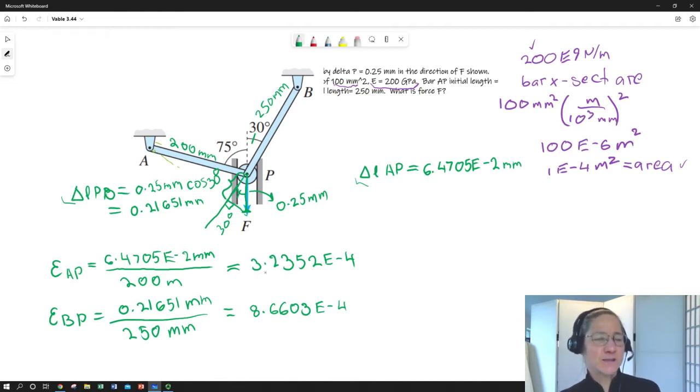We would also expect maybe a little bit more strain in PB, simply because it's oriented closer to the direction of known strain. As an aside, we don't have any deflection, any displacement perpendicular to the vertical and then the horizontal, because we have these bearing surfaces. So we can imagine that there's a force from that bearing wall being applied to preclude any kind of stresses that would result in deformation in that direction. So everything is exclusively in the vertical. It's a bit of a 1D problem from that standpoint.